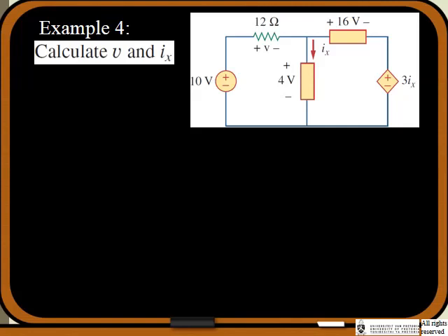If you just look at Ohm's law, we can't use anything here yet. Again, if we want to know what the voltage is across a resistor, we could ask, do we know what the current is through that resistor? No, we don't. There's no current information, so we can't use Ohm's law in this case.